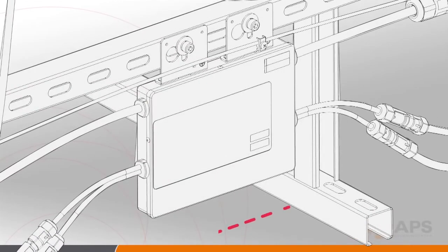And it is extremely important to allow at least 3/4 of an inch between the roof or mounting surface and the bottom of the inverter. This spacing is important for cooling airflow to reach all surfaces of the inverter.